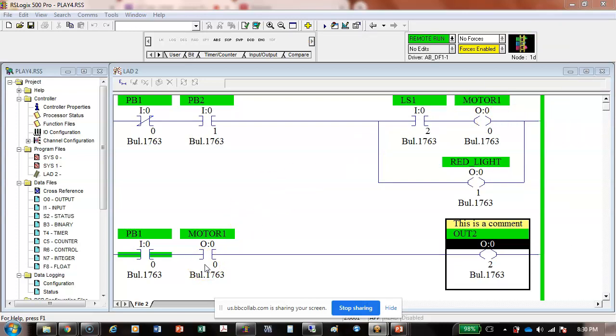That's a normally open contact being controlled by this. This is not hardware. That's software. This right here is controlled by an input connected to an input port. That is an examine if closed instruction. So right now I have that switch closed. This is an examine if open instruction. Right now I have that switch closed, so up here it's false. Down here it's true. So that's very important, and we're going to push that and push that.